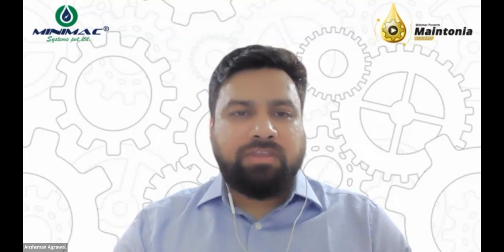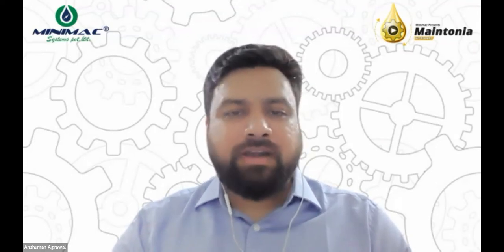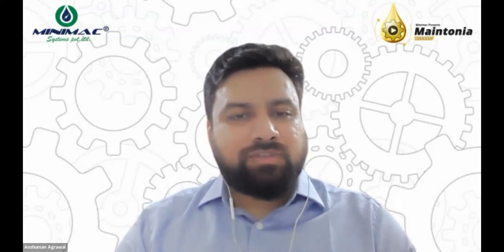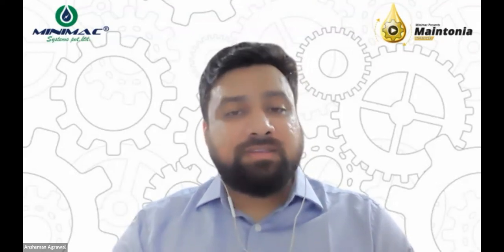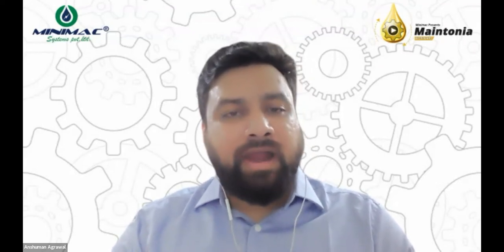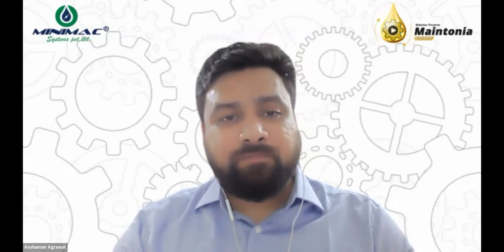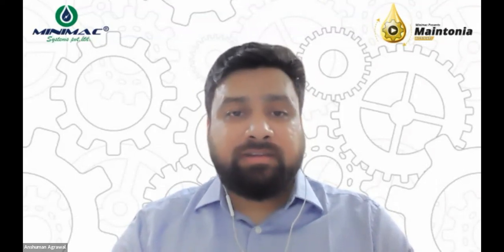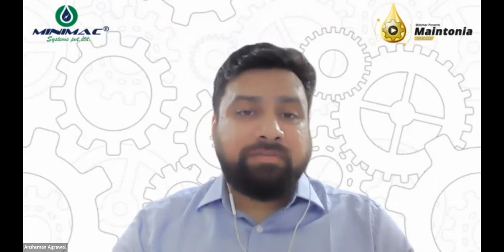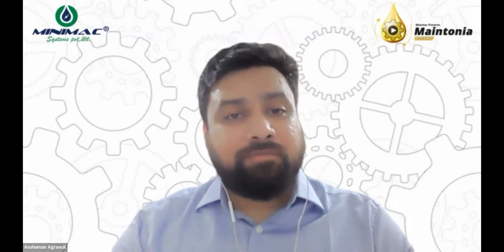And see, whenever you are giving a solution, you need to understand what you are going to give the solution for. So when we have free water content in the lubrication system, centrifugal systems, coalescer systems, or gravity separation systems are all highly applicable and used across. But while we are talking about control systems, we certainly discussed during the webinar that these do not have free water content. And that's the reason why we need to move beyond centrifugal purifiers and certainly avoid them.